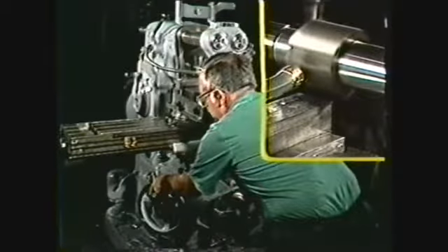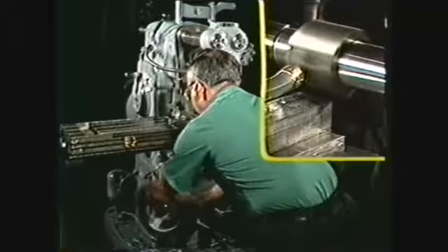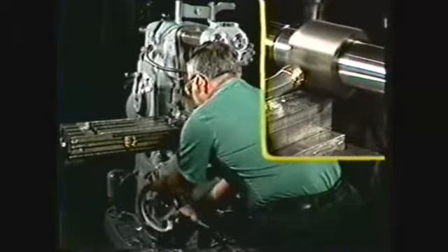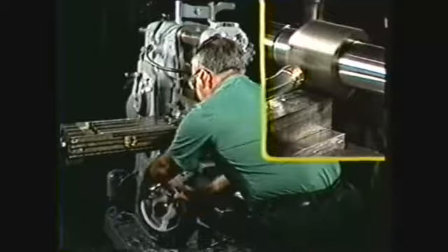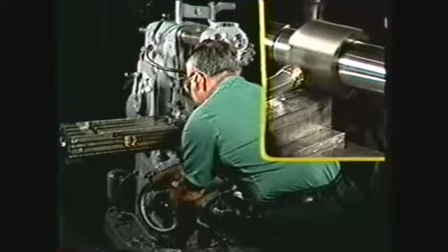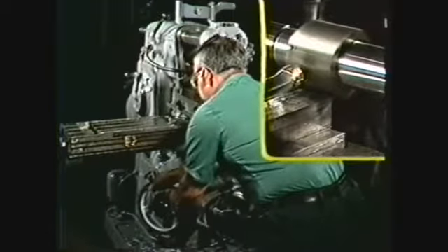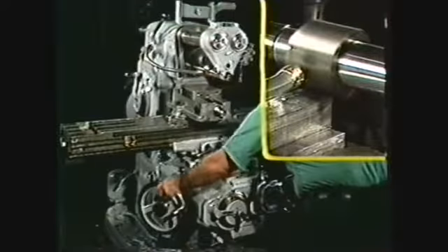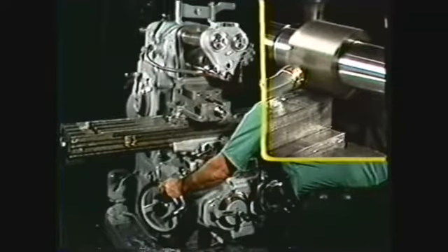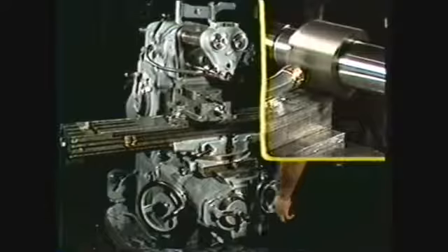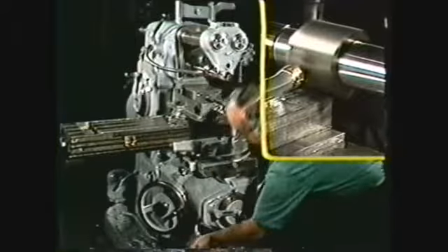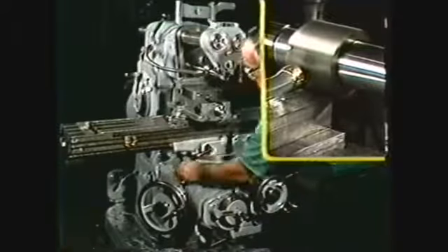Raise the table 200 thousandths to take that depth of cut on the workpiece. In plain milling, depths of 100 to 200 thousandths are used for roughing, and depths of 15 to 30 thousandths are used for finishing. Tighten the knee lock and cross slide lock, but keep the longitudinal feed unlocked during this operation.